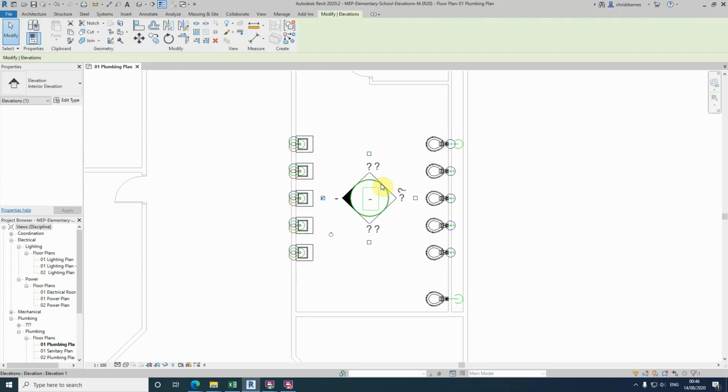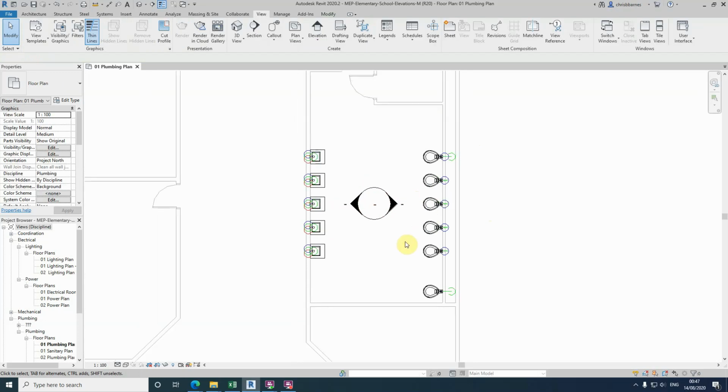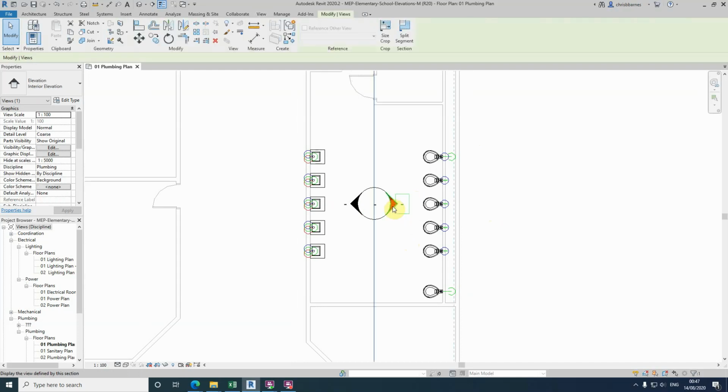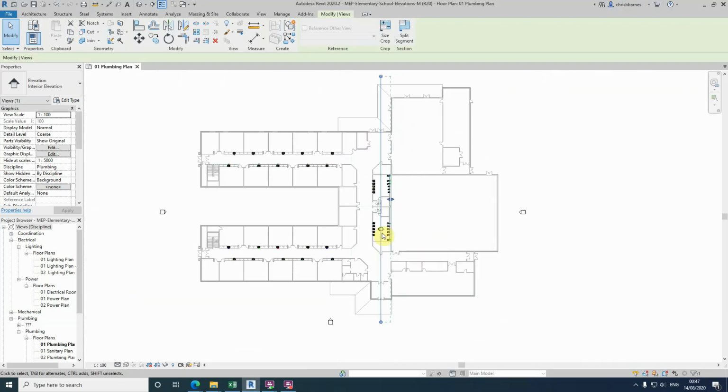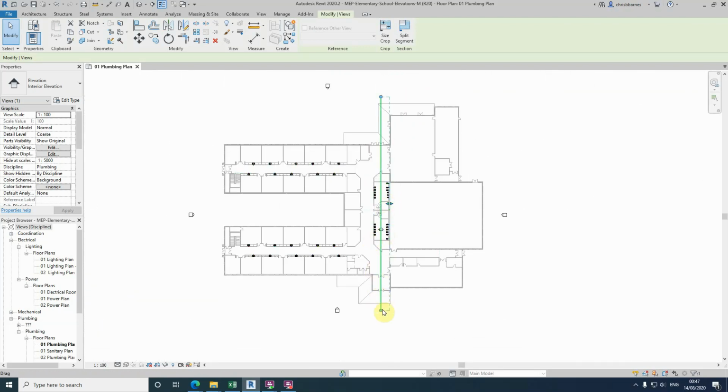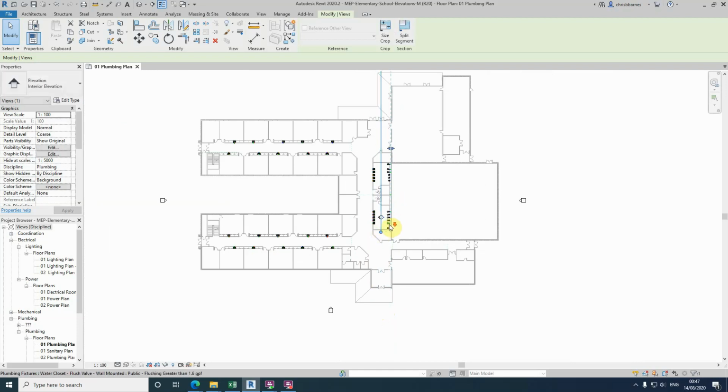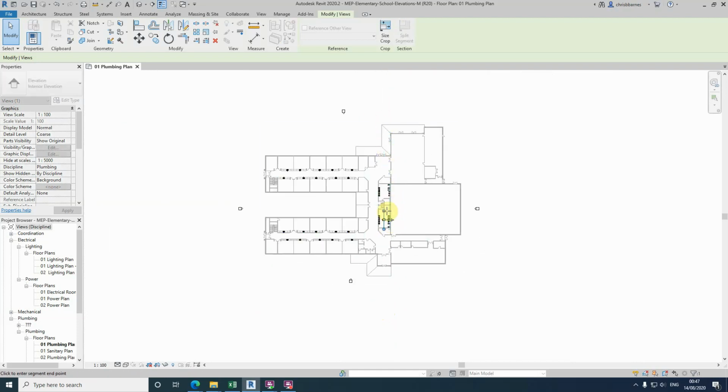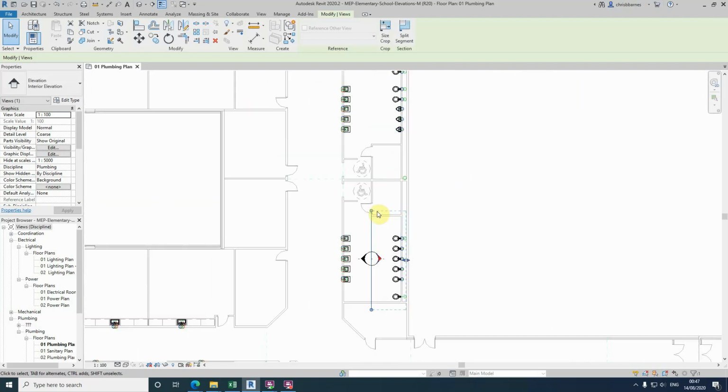Click on the box on the circle, and then we're also going to create another elevation by clicking this tick box here to point towards the toilets. If we click on one of the arrows, we can see with elevations it takes us a wide area, so we're going to just zoom in, till we're sort of covering something like this.